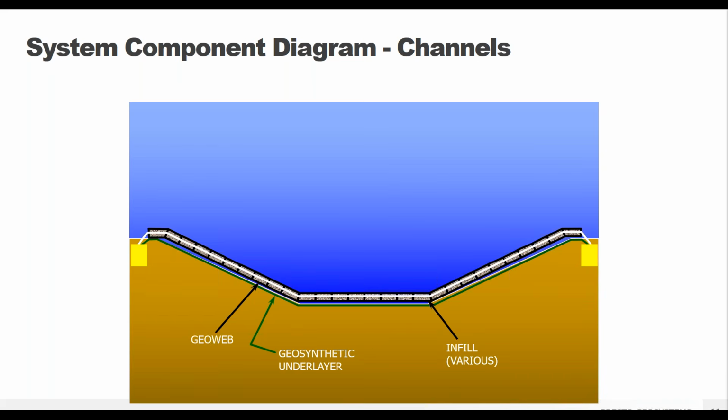Okay, so then you fill in your GEOWEB panels with whatever desired infill material you choose, whether topsoil, aggregate, granular material, or concrete. And then the GEOWEB system can handle water flow. It is designed to create a stable channel surface even when the maximum velocities and shear stresses do occur. And we are going to talk about those numbers in just a minute.